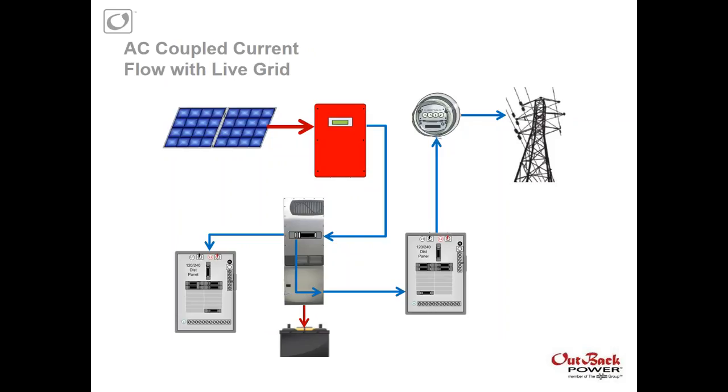Today, the typical system just looks like this, and everything that you see here from the PV, the grid tie inverter, come down here, you got your main load, your meter, and your grid. That's a grid tied system. You take this line and all you're doing is just cutting it, and you're giving yourself a critical load panel, a battery, and an Outback system.